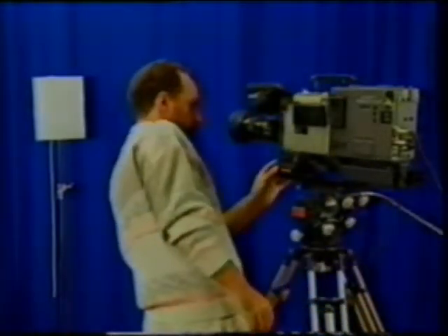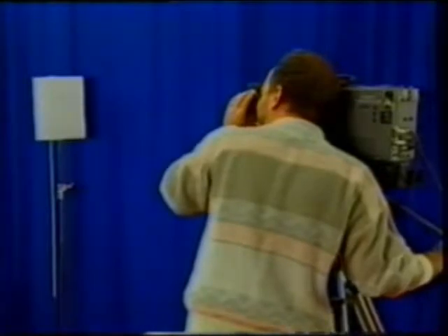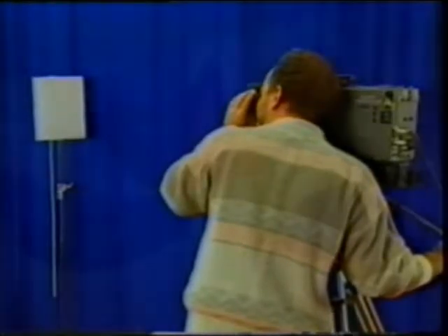By now, you've probably figured out there is a difference between electronic visual reproduction and other visual reproductions. Painting, for example, is a subtractive system. When you mix the primary colors, you get a dark brown or black. Video is just the opposite. It's an additive system. Mix the primary colors in the approximate amounts of 30% red, 60% green, and 10% blue, and you get white.